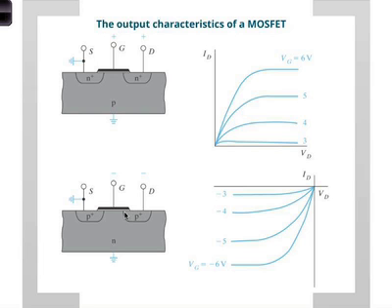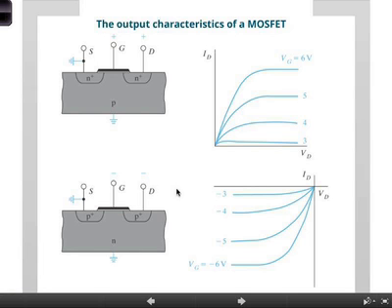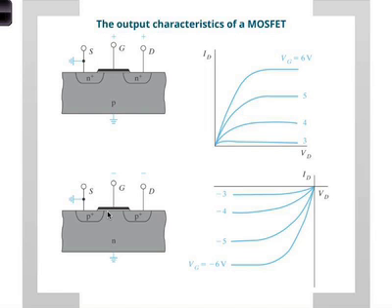That's relatively simple. The drain to source, of course, it's a P-type channel. So the holes will flow from where to where? Okay, it's a bit of a trick question because the drain and source are arbitrary, right? Remember we talked about, in fact, you mentioned this last class, they're symmetric, I can pick what I want.